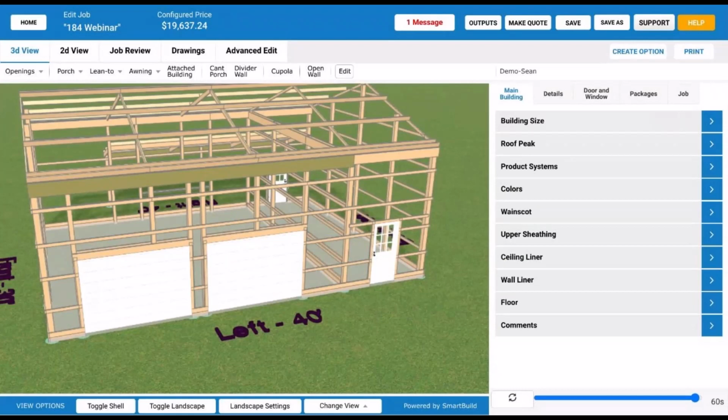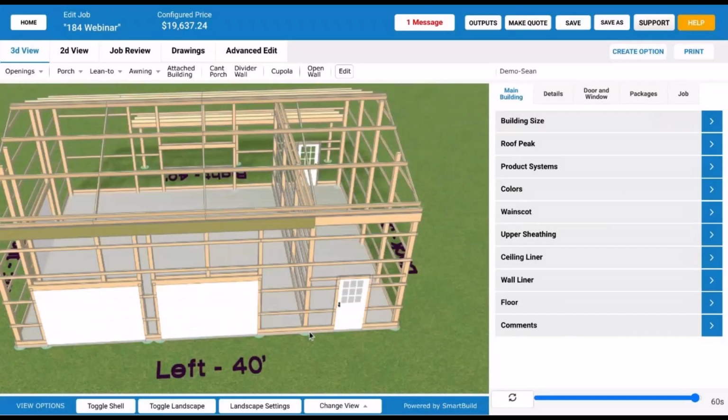That's the other enhancement we were talking about, which was to basically say, look, when you're putting your structural posts on the wall, assuming that you're not putting one for every truss, the first thing we're going to do is look at where your openings are, your structural openings. And any of those structural openings, the spaces between those we will treat as if it was a wall in and of itself.